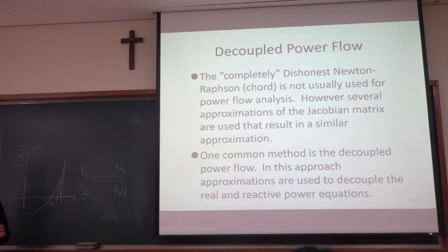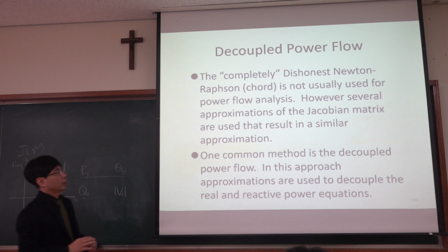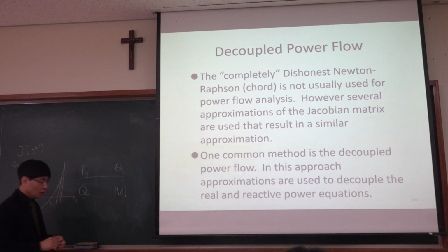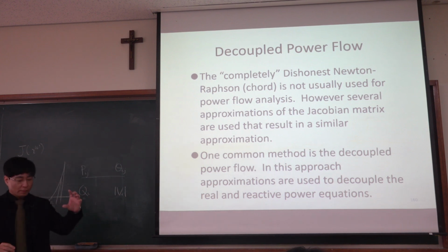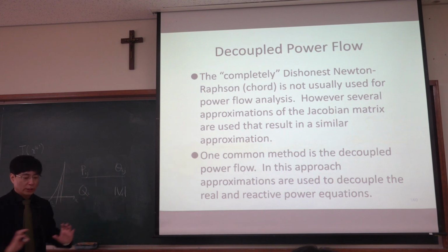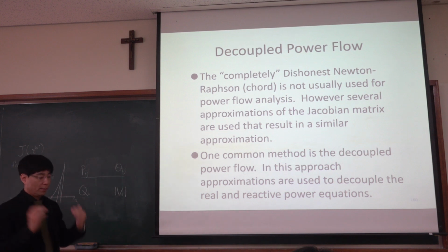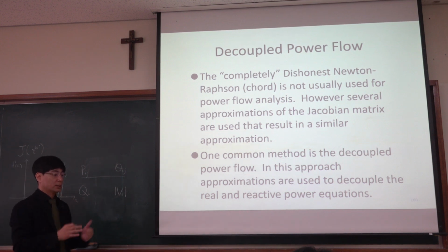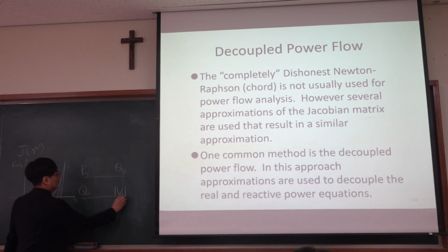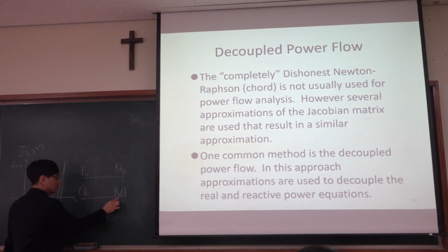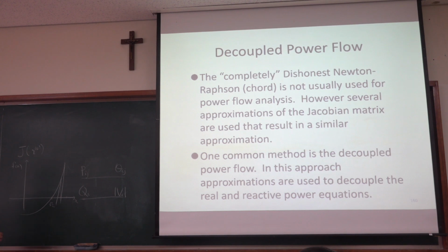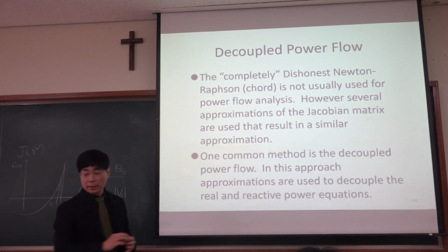You may remember that in the beginning of our class, when we talked about power factor compensation, we need to inject reactive power at the load side by adding a capacitor, or capacitor bank. That is because reactive power mostly determines the voltage. That's why this professor studies voltage and reactive power in the distribution network. We will see why that is.